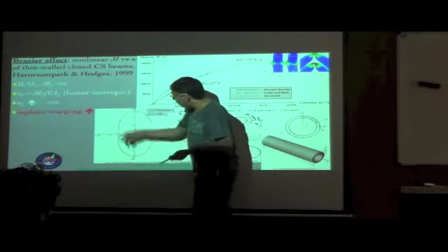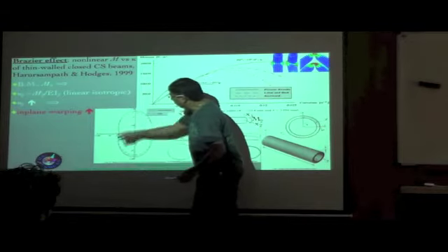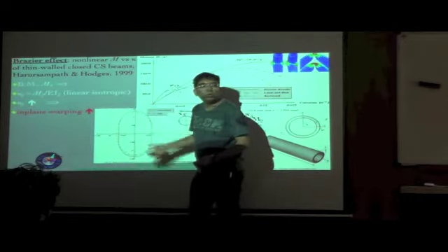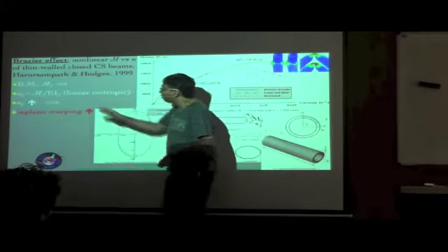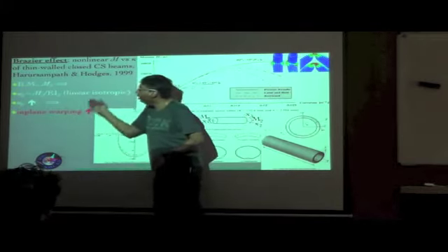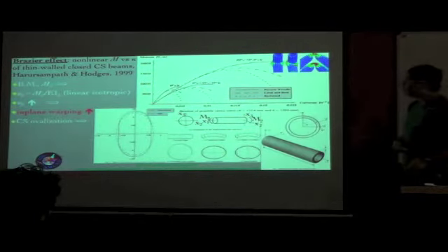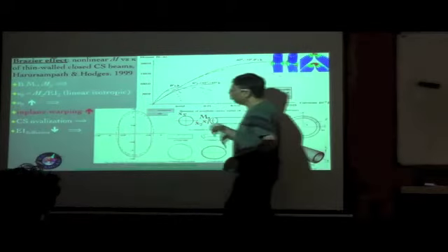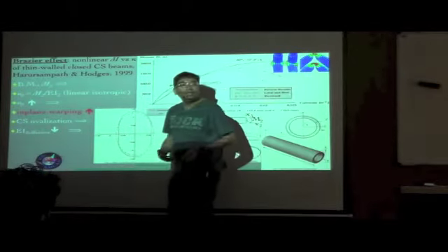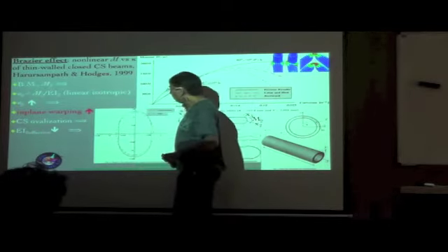But the in-plane warping here is much more dramatic, and you basically see the so-called ovalization of a circular cross section. As you keep increasing your kappa 2, your in-plane warping also keeps on increasing. And this cross-sectional ovalization eventually leads to a drop in the bending stiffness so substantially that the limit moment is reached.